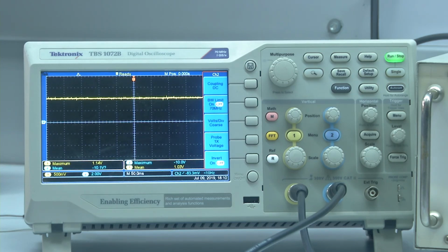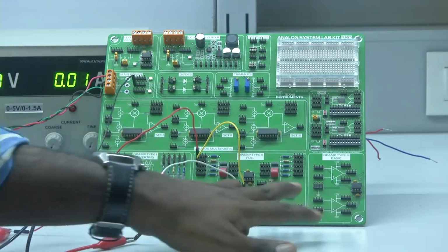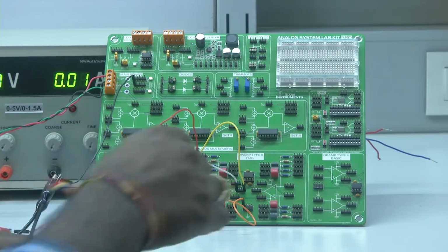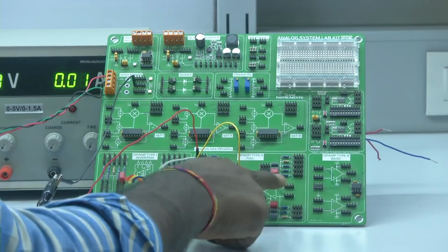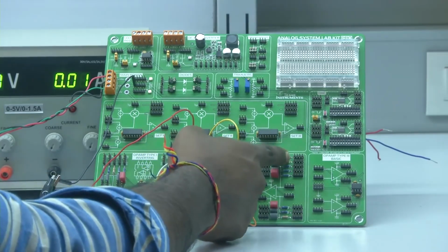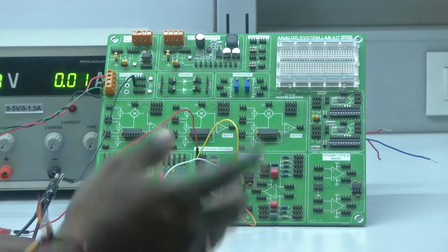So in order to correct the phase, what we do is use another stage, which is also an inverting amplifier configuration with a gain of 1. Let's see how exactly I am building the inverting amplifier configuration with a gain of 1. Since we have to realize another stage using inverting amplifier configuration with a gain of 1, I will use this particular stage, which is OP2B. Even in this case, we have dedicated jumpers for the negative terminal, positive terminal, as well as the output. Also, the board has been provided with different resistances, but in this case, since we require a gain of 1, the input resistance should always be equal to the feedback resistance.